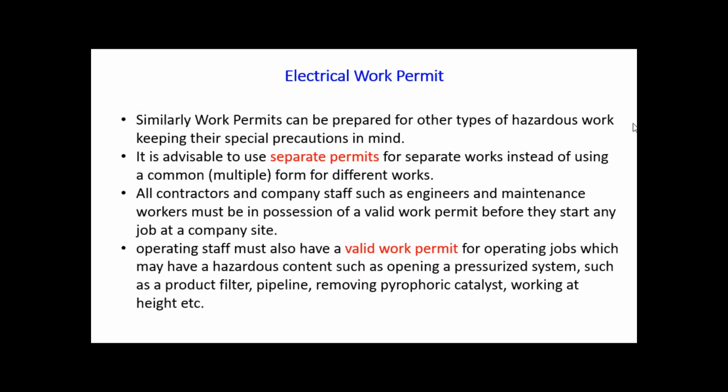Then similarly, work permits can be prepared for the other types of hazardous work, keeping their special precautionary measures in mind. It is advisable to use separate permits for separate works instead of using a common form for different works. Whatever I have discussed, hot work permit systems have different hazards, and from that point of view, the questionnaire or the checklist is different. And the expert persons, the contractor, subcontractor, worker, are also different.